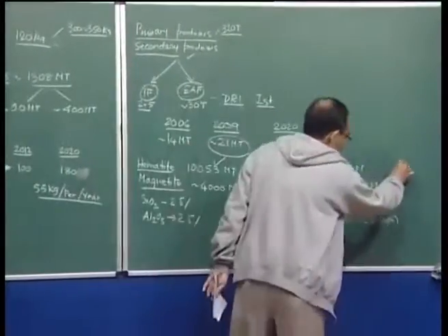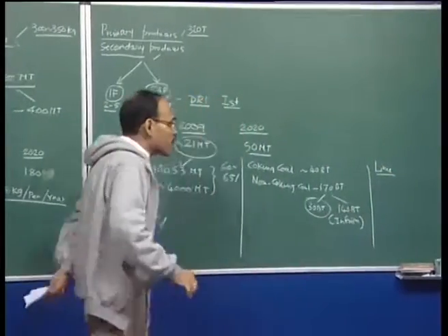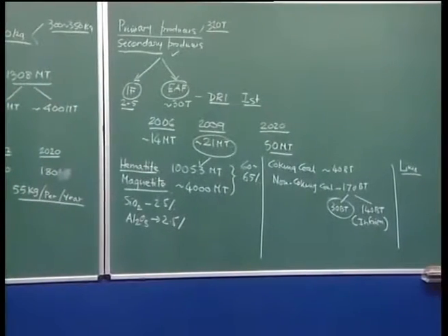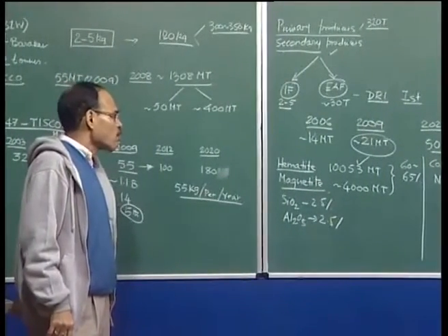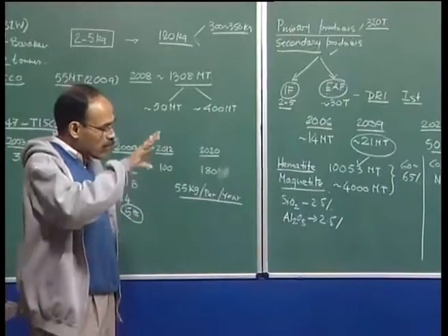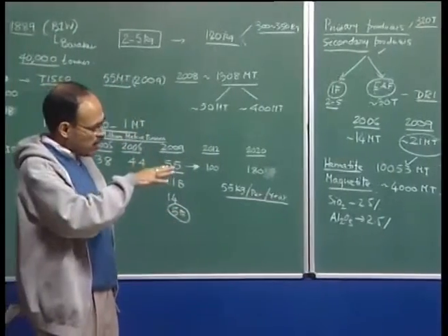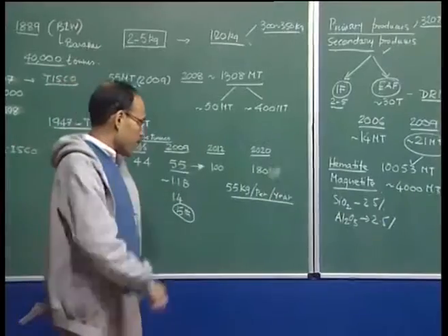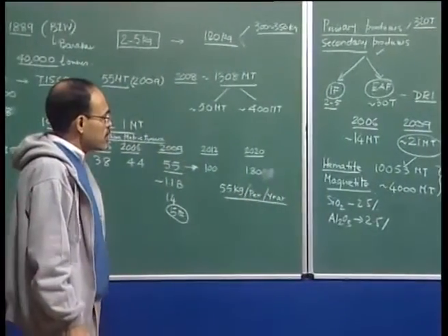We also have good quality lime, or the fluxing material, available in the country, but so far as Indian limestone is concerned, it tends to be a little bit hygroscopic. That is the only demerit, but other than that, as far as the silica is concerned, this is relatively less. The lime has 50-60% of CaO, which is a very good quality as far as the making of iron and steel is concerned.